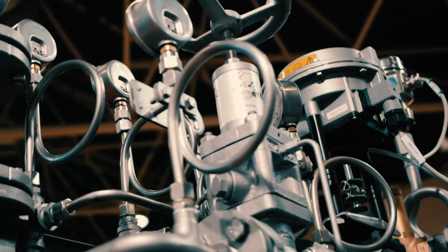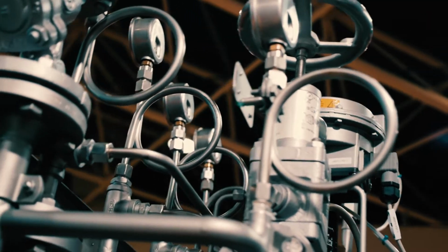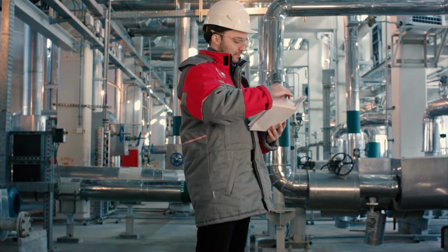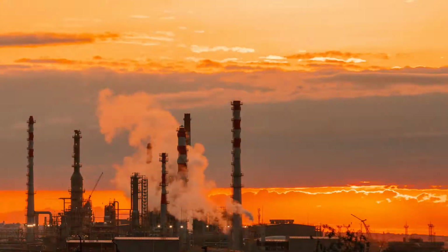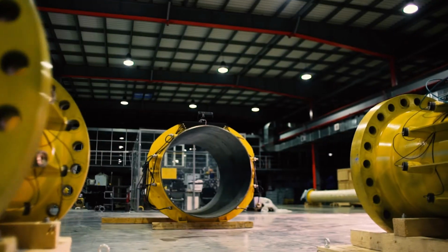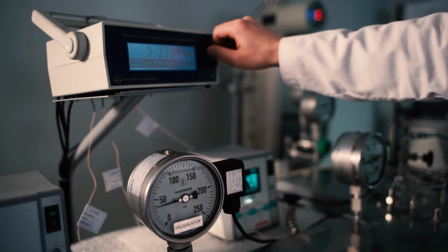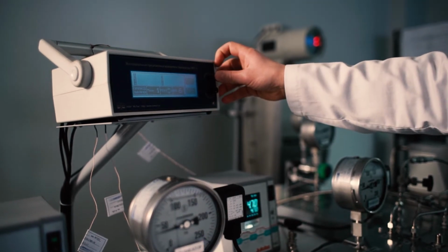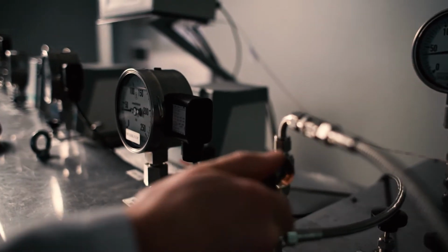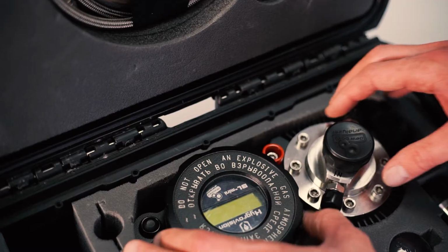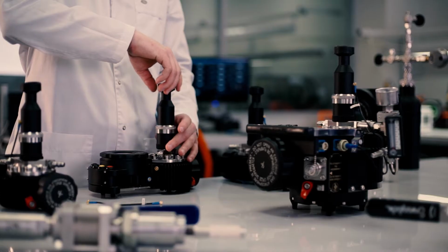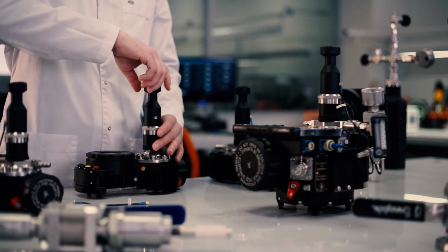In addition, it has become increasingly necessary to install modern gas analyzers that have the ability to measure the hydrocarbon condensation temperature with a high degree of accuracy. Today, the most accurate method for measuring these parameters is the condensation method. This uses an optical system to register condensate formation on a chilled surface. This method is a first principle measurement. It is straightforward, reliable, and resistant to harsh conditions.